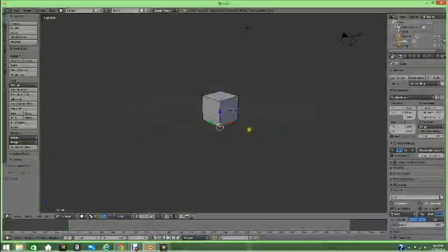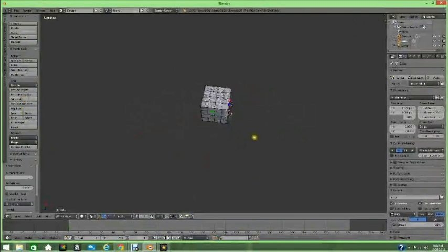In order to explore the other selection tools, we need to go ahead and subdivide our box. We'll select it using our box selection tool and hit subdivide. We'll do this a couple times in order to get a more complex cube. We're going to go ahead and hold our Alt button down while we select a line. You'll notice that it selects the entire ring around the box.